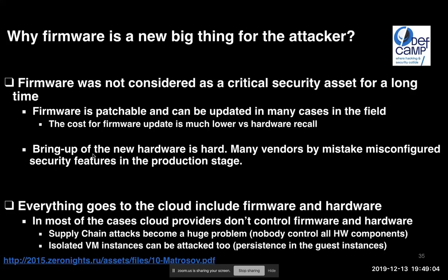Bring-up of new hardware is very hard. Basically, when you try to boot new hardware the first time after manufacturing, many vendors make mistakes and misconfigure things, because the biggest part they care about is booting the platform. And sometimes they also forget to configure security features back at the production stage.